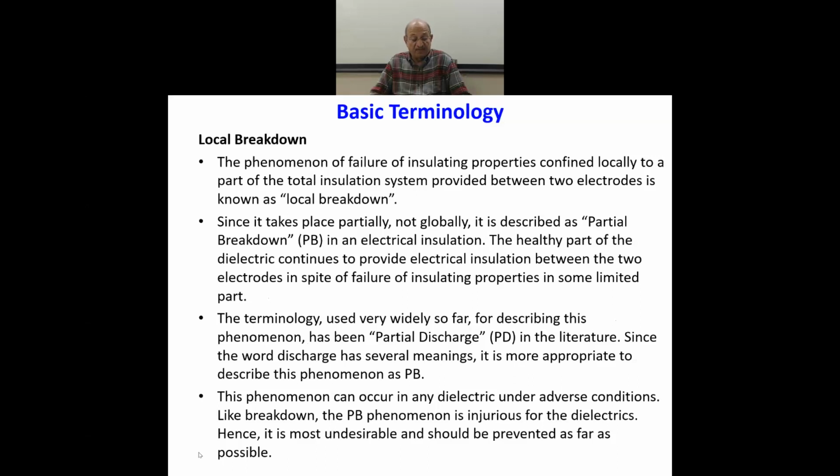This phenomenon of local breakdown or partial breakdown may occur in any dielectric under adverse conditions. Adverse conditions could be when there is a weak point in the insulating material or at a position where the electric field intensity is very high, unlike in the neighborhood.